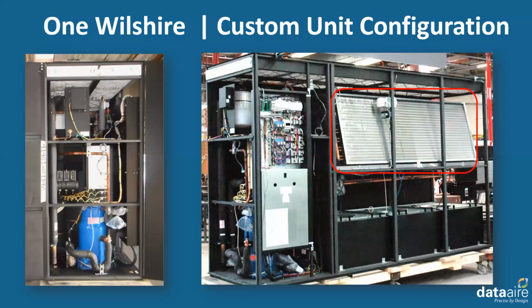The energy saver water coil is on the outside. The DX refrigerant coil is behind the energy saver coil in a nested A-coil arrangement. Below that are the direct drive plenum fans. Each one has its own plenum. This increases efficiency, and it allows each fan to be pulled out individually for very easy changing of the motor.